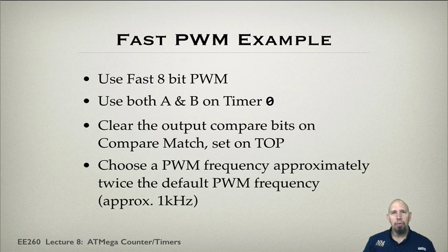You'll find that when you hook up a motor to the pulse width modulation, you can actually hear the motor humming because of the frequency of the pulse width modulation. If you change the frequency, it'll hum at a higher frequency. It's very common for industrial pulse width modulation systems to use a very high frequency, like tens of kilohertz. The motor will still hum, but at a frequency you can't hear, so it's not disturbing to you. Otherwise, the humming from a motor when you're using pulse width modulation can get kind of annoying.